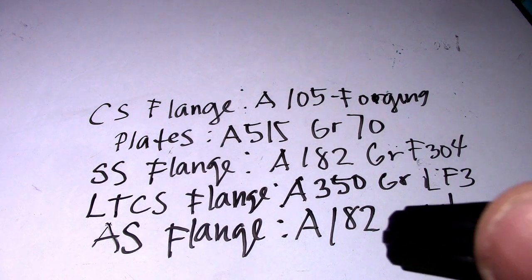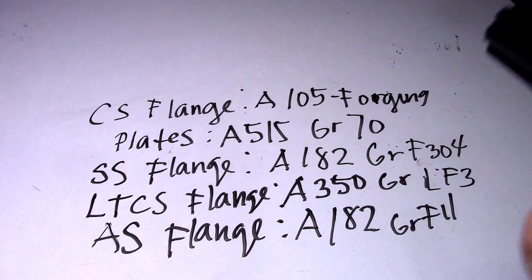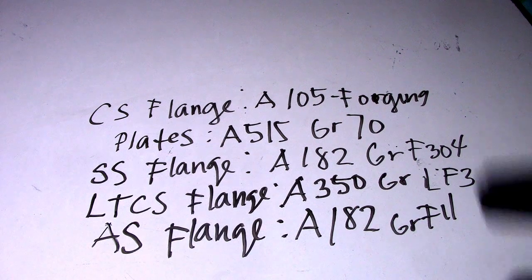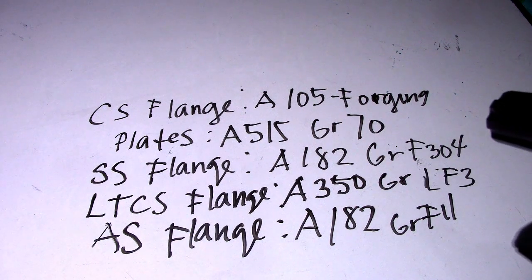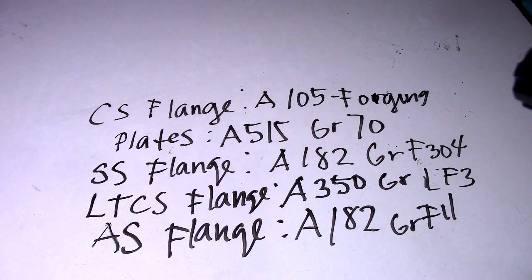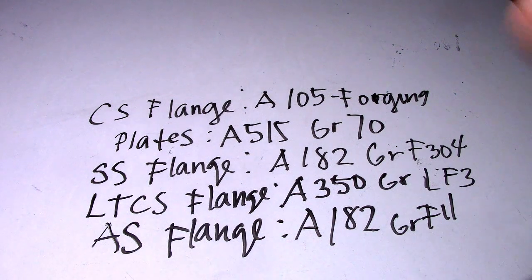And they also have SS321. This is also a stainless steel with the same chemical composition as SS304, but in addition it contains titanium, which is a stabilizer.